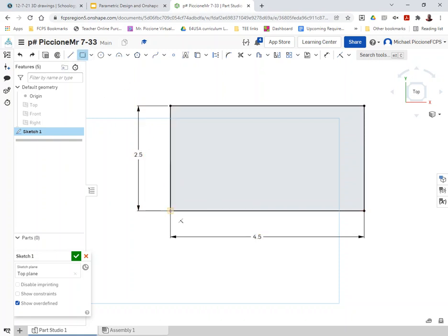We said there was a shelf over here that was 5/8 wide, so I'm just going to draw a rectangle. Snap it into the opposing line, and then we use edge to edge to make it 5/8 wide. 5 divided by 8. And then I can use the rectangle tool to draw the little squares over on this side.